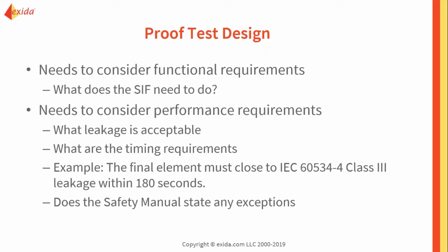Once again, think about when you're designing your proof test, you want to design for those failures not detected by automatic diagnostics. Think how it can work functionally and performance-wise, but not waste your time already proving and testing what you know works, and instead design a test that looks for those undetected failures that your diagnostics are not already checking for.